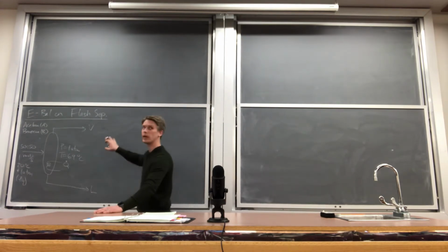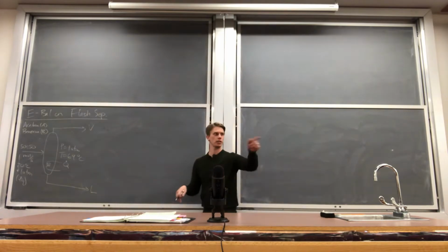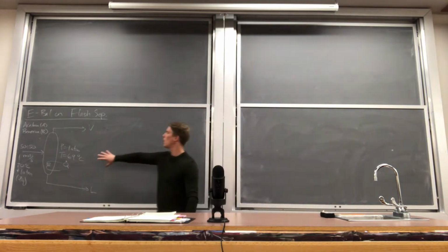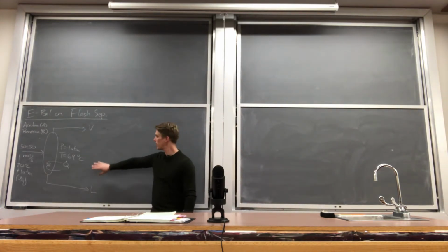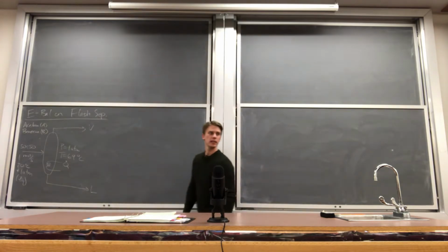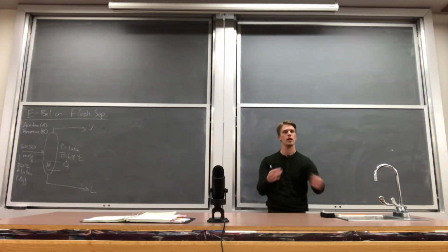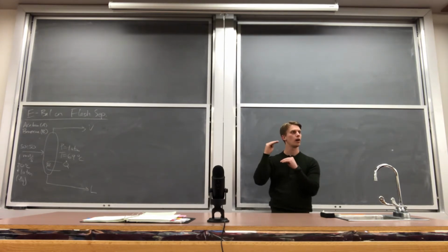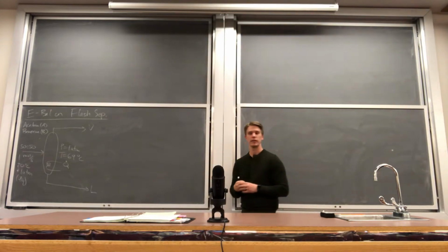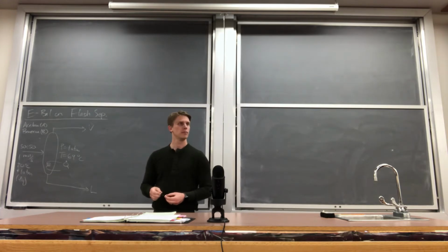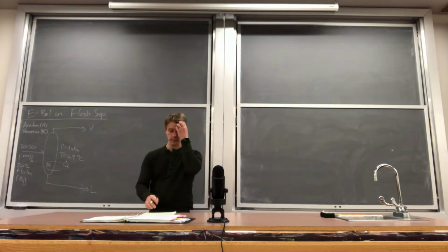If they're not in equilibrium, we can't use any of the tools that we've developed so far with Raoult's law. Question? Will that always apply to flash separators, that the top and bottom stream will always be at the same temperature and pressure? Yes, for flash separator, we're using one equilibrium stage. And at an equilibrium stage, you have to have the same exact conditions. The same is true for liquid-liquid separator as well. So if you wanted to use a triangle diagram for liquid-liquid separation, you would have to assume that the top and bottom streams are in equilibrium. Right? So that's how you could actually read off the triangle diagram. If it's not in equilibrium, then we can't use any of the thermodynamic tools we have. We have to somehow then estimate what it might be.